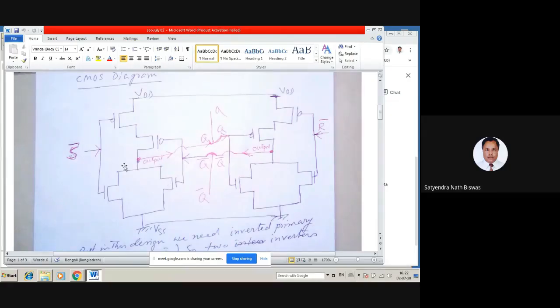And now here, we need to connect the two gates. In order to connect the gates, I am switching the bottom PMOS on the right side, placing the gate on the right side so we can connect those two gates. And these two PMOSes are connecting the left side. You see the PMOS and NMOS here connecting two gates, and that will be one input. And this one PMOS here and the NMOS here, these two gates will be connected, and there will be another input. Right, so there will be two inputs, and the output will be coming from here, right?